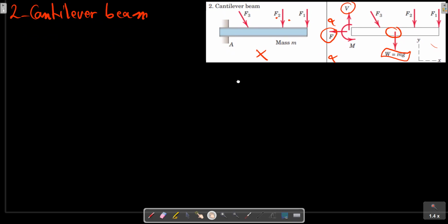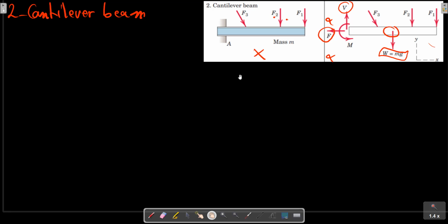In the free body diagram in this example, we have represented the somewhat complex system of forces which actually act on the cut section of the beam by the equivalent force couple system, in which the force is broken down into vertical component V and its horizontal component F. The couple M is the bending moment in the beam.